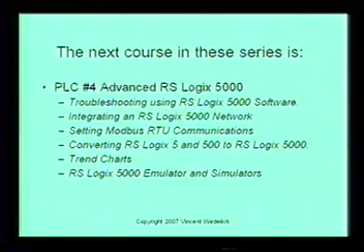And then we'll go through converting RSLogix 5 and 500 to RSLogix 5000 code. You can go from 5 and 500 to 5000, but you really can't go from 5000 back. We'll go through the trend charts; there's actually a trend function that you can use. And then we'll go into more detail on these emulators and simulators and play with those a little bit more as well.